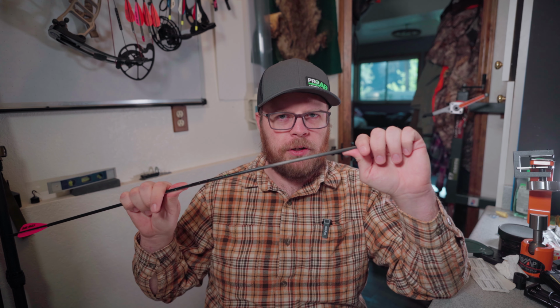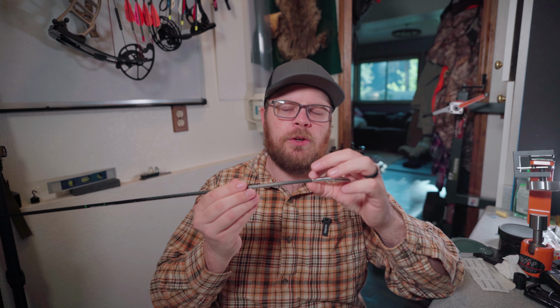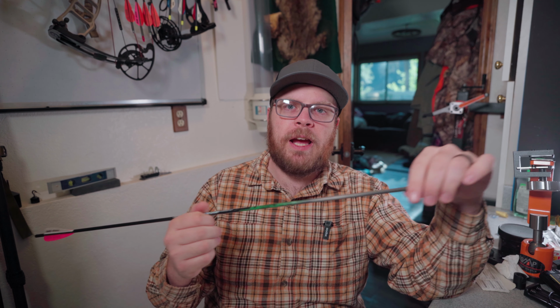There are two materials, steel and titanium, which do overlap slightly with our carbon arrow ultimate strength. However, generally speaking, we're going to have failure in our component before we have a carbon shaft break. Now that's assuming that we don't split the shaft or perhaps crack it. Our component is most likely going to be our point of failure first over the carbon shaft. We want to design a component that can resist a lot of our stresses in the front of the arrow shaft during impact without bending. So if we want to reduce our chance of bending, what do we need to do?